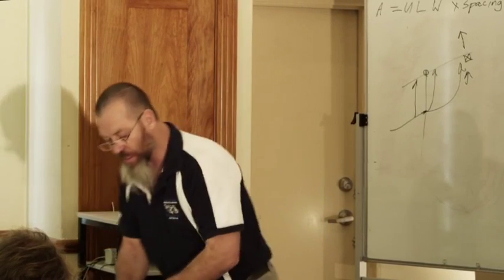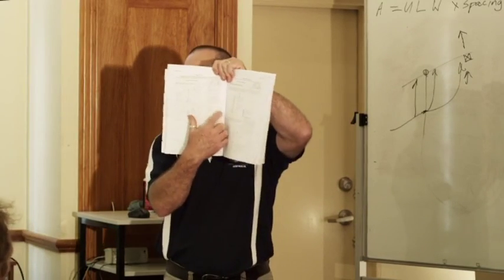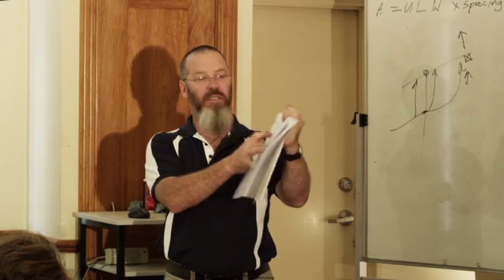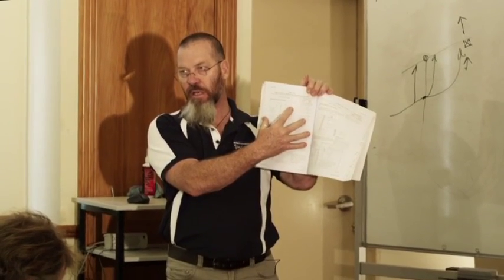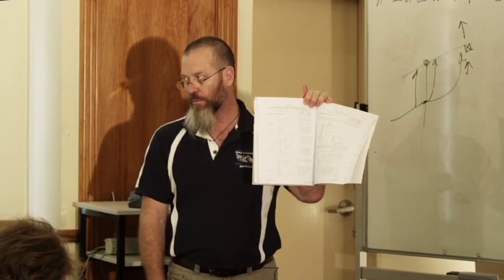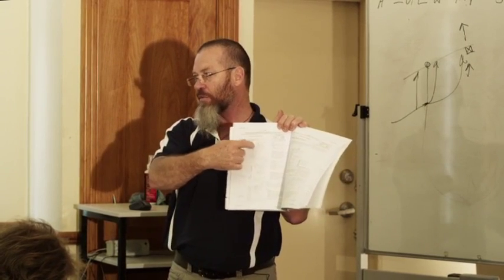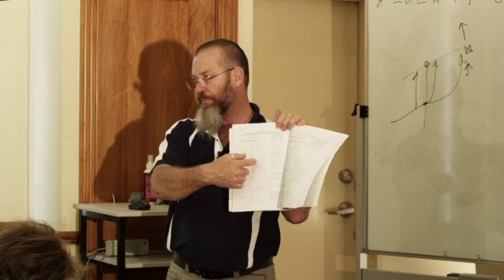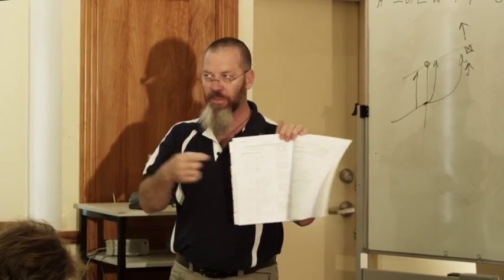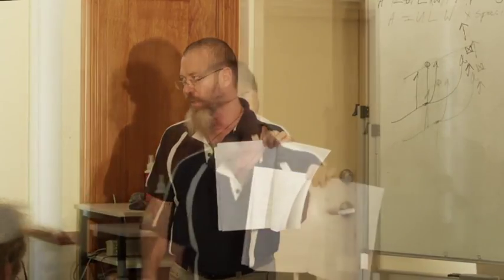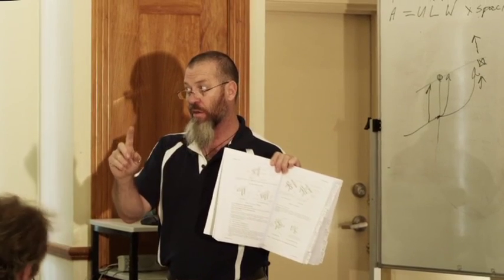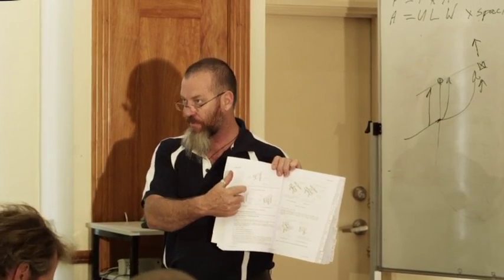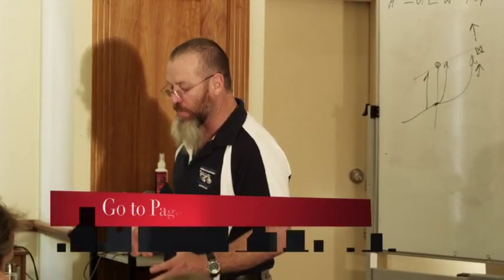Also, if you read this note here in the corner there, basically what that note says is whatever resistance value you've calculated for that truss or rafter over the top of that opening, it has to be transferred down into the lintel. So if you've got 2.9 kilonewtons, for argument's sake, you have to transfer that down into the lintel. And this is one of the reasons why the project builders now are putting the lintels right up underneath the top plate. So you see there, they've got the lintel right up underneath the top plate. The reason is, and I kid you not, that every time they do that, they save half a metre of metal strapping.